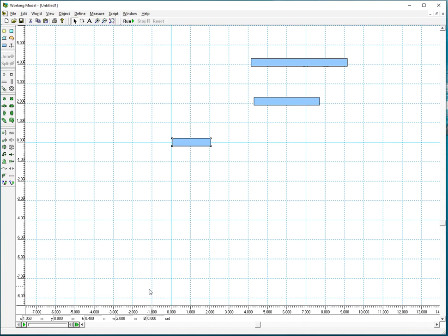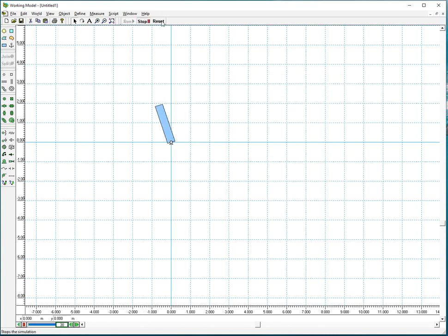I bring it to where it's at. I'm looking here, 1.05. I make this 1, and y was 0. Then the center of mass is at 1 and 0. It means that this end is at the origin, and I could snap a motor. Okay, I hit run, and of course I have gravity acting. Two are falling, this one is rotating.